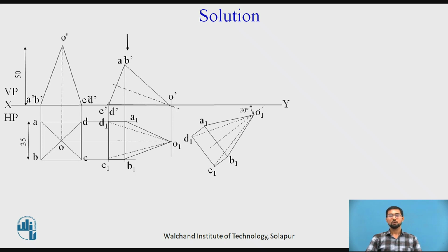If you observe here properly, the apex point is nearer to the XY line, that means it is nearer to the plane, and the second thing is it is away from the observer. The observer is viewing from the bottom side. That arrow mark itself is the observer, and it will not be visualized nearer to the observer, so it is away from the observer.